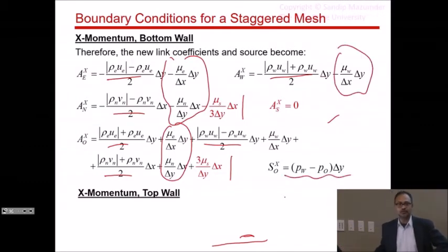Source will also be 0 because I've set pressure equal to 0 everywhere, right? So when I solve my momentum equation, it's almost like I'm solving a Poisson equation for velocity, a diffusion equation. Now, if my entire source vector is 0, like we are saying here, then of course the solution is going to come out 0. Because there has to be some source. I mean, if I just solve all equations equal to 0, the final solution will be 0. Okay? So there has to be some source.